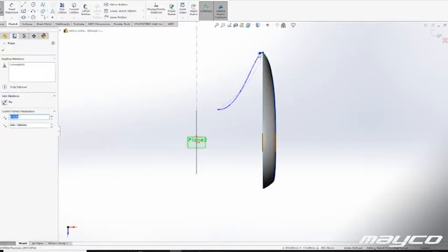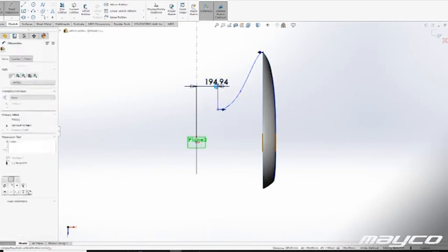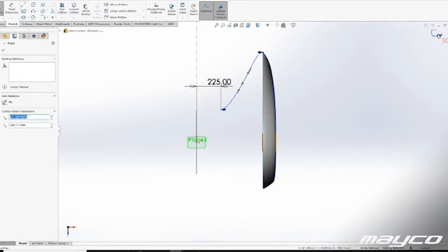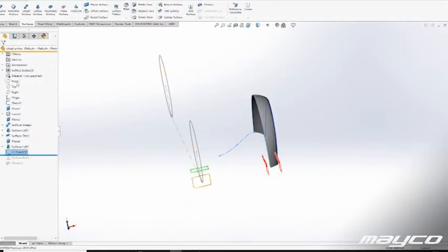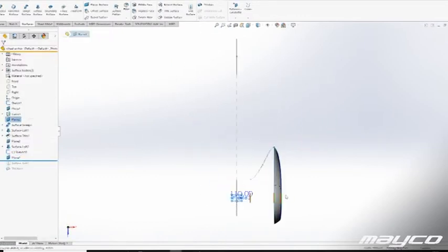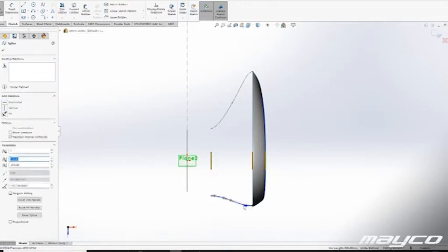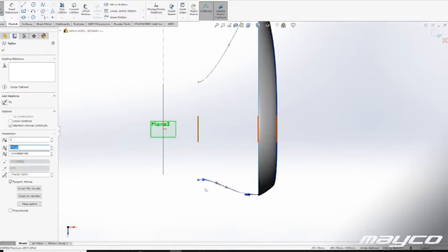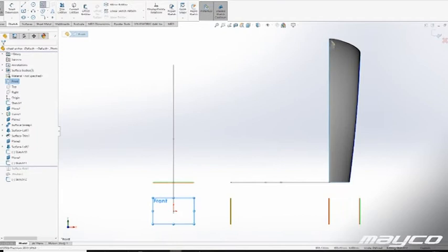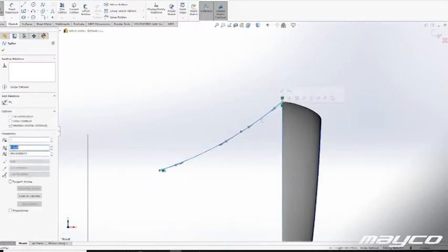Very often it is required that you work with 3D sketches. First thing, if you made a 3D sketch, click somewhere in your screen, because if you don't and you want to start a new one, you continue in your previous sketch, and this is very annoying. It still happens a lot, and when you want to make a surface out of sketches, it'll say, hey, this won't work because these sketches are in one tool.